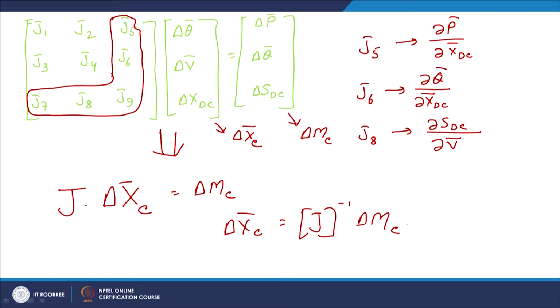For example, if there are 10 HVDC links in the system, and corresponding to each HVDC link there are 5 unknowns, then there will be 50 more unknowns. The unknown vector, the known vector, and the Jacobian matrix will all increase substantially, and so the computation burden will increase substantially.